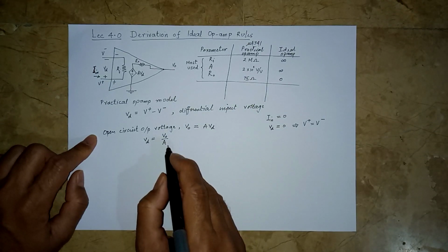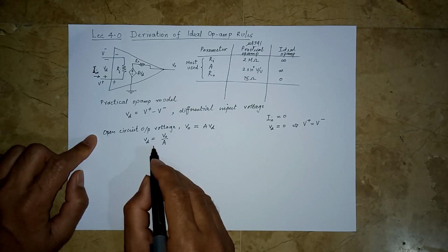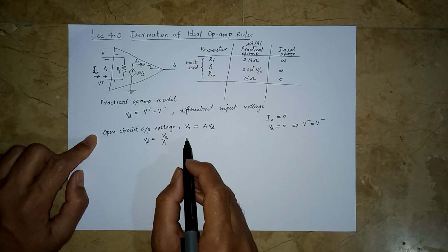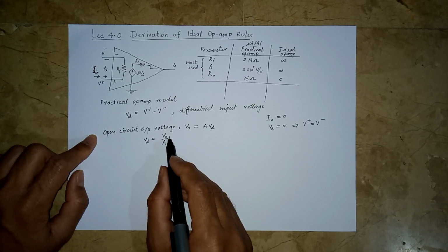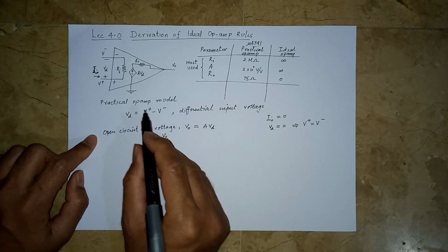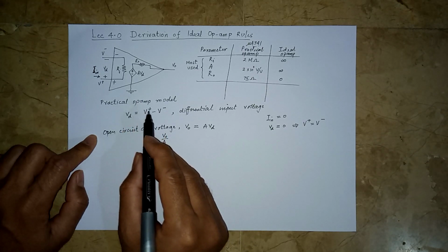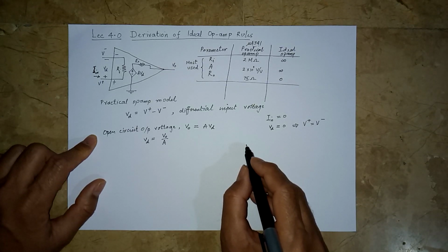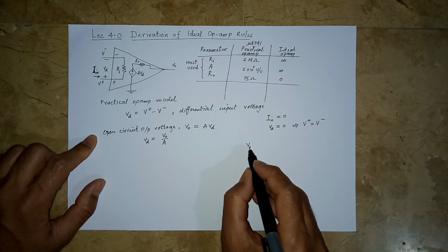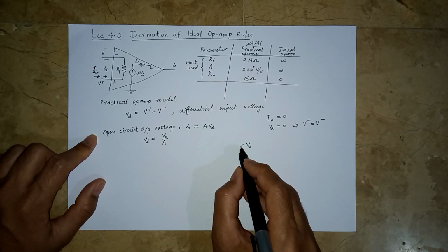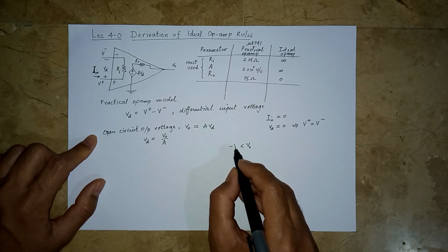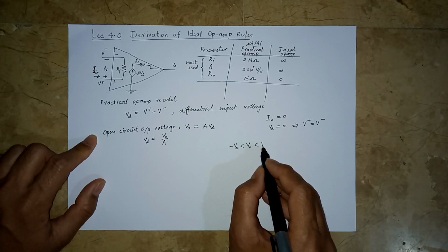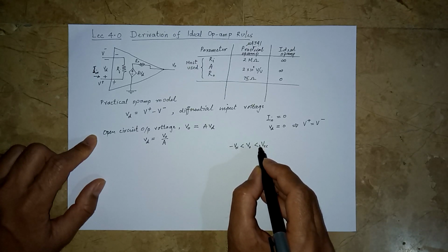So here, if we use typical configurations, then we know that the output voltage, as I might have mentioned somewhere earlier, but let me put it categorically here, the output of the op-amp VO cannot go beyond the two supply voltages that we use. So minus VCC and plus VCC limit the output voltage.